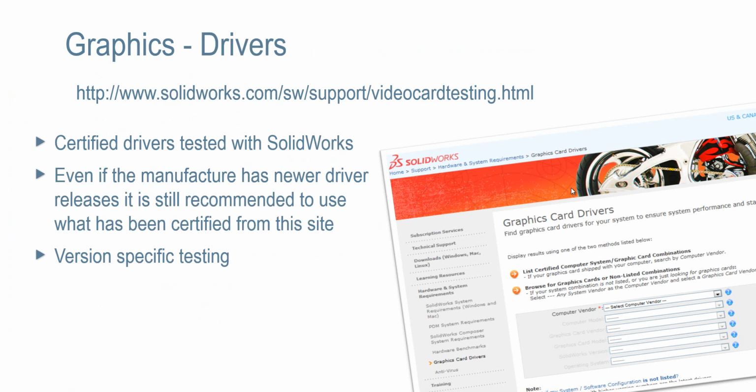So drivers, again, if you're unsure about your driver, either use SolidWorks RX or go to this link and fill out the form, which you can see on the bottom right of the screen, and then it'll tell you what driver you need, and you can just download it directly from the SolidWorks website and then install it from there. You know you'll be running the right driver.